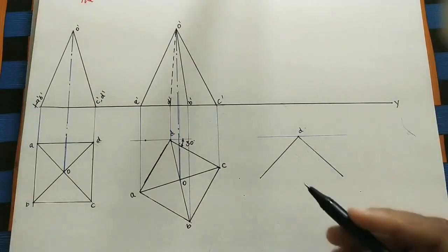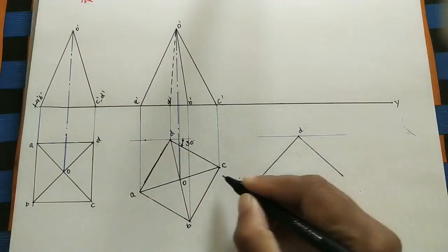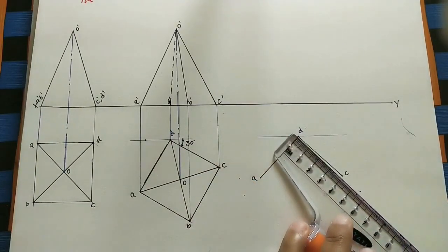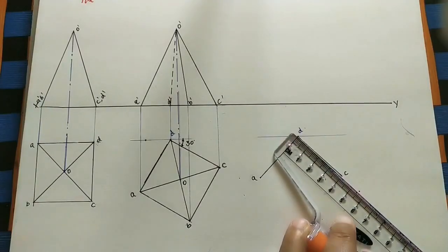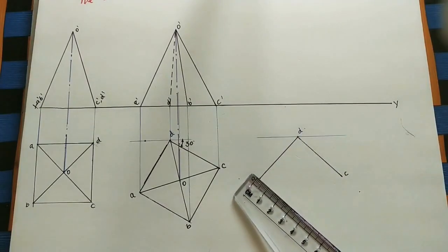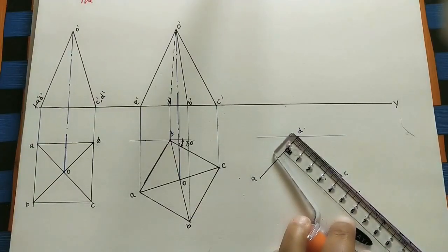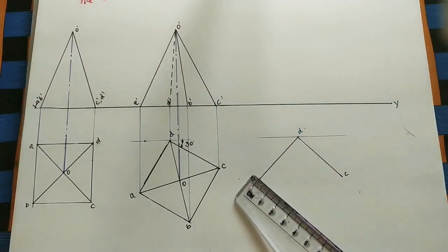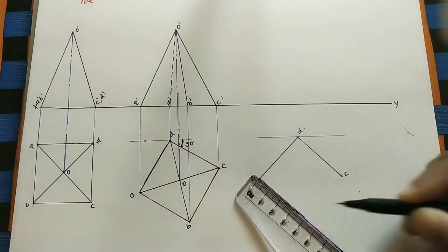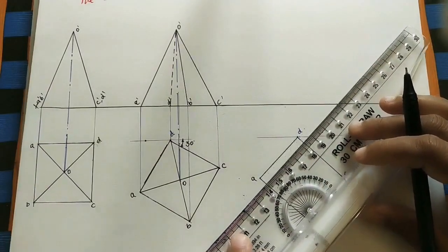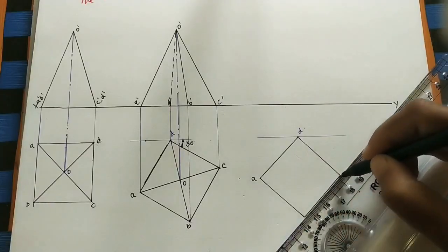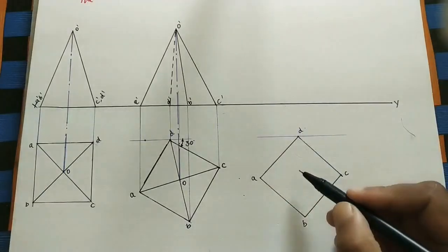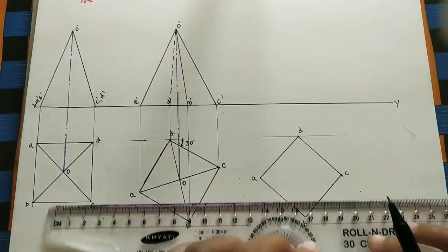Now here mark the corners. D here we have marked, here A, here this point is C. Okay, do the parallel lines at the other sides also of 4 centimeters. Take a 4 centimeter parallel line here. And take this as reference. Do one line here, a parallel line. Okay. Mark this corner, it is B. So B and D should come on the same line. After that, mark the apex. For marking the apex, join opposite ends.